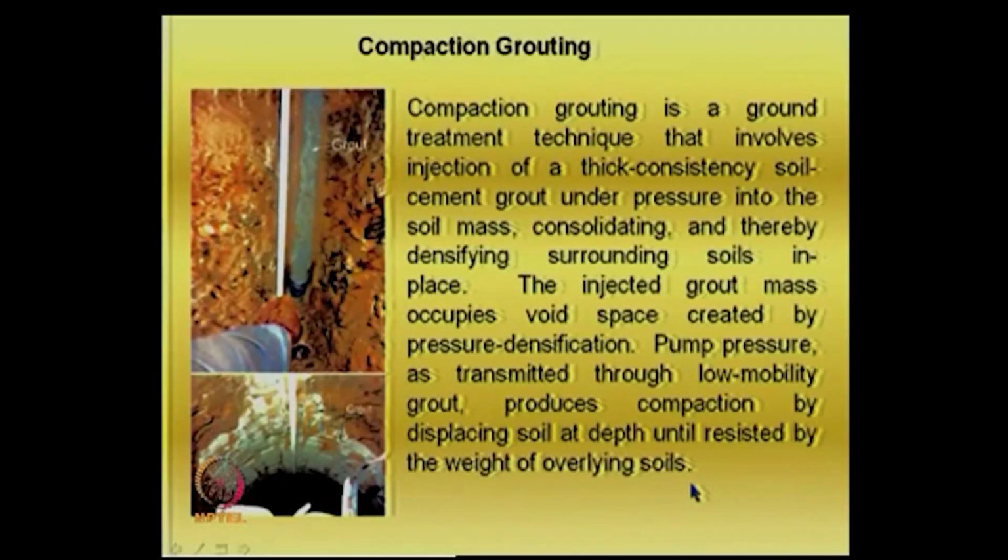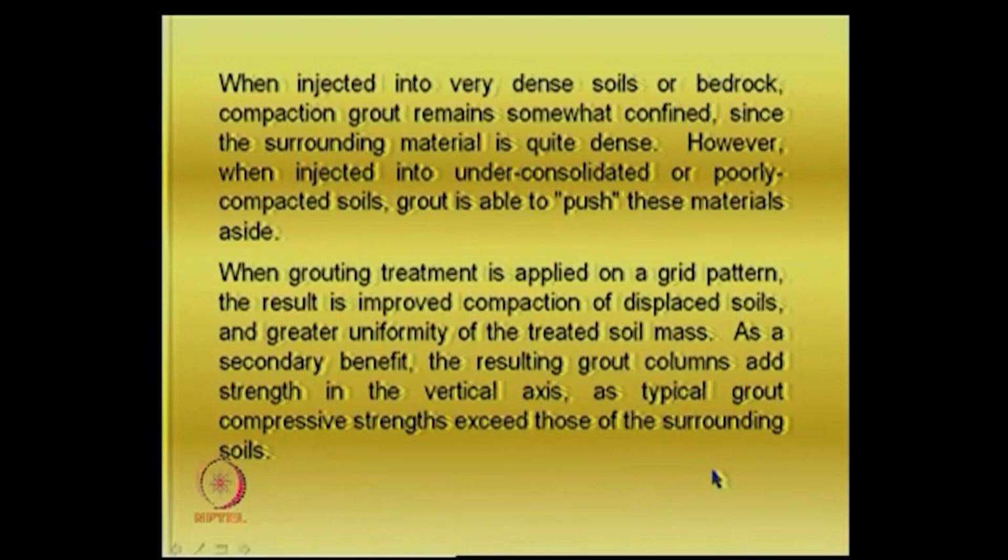That is why you just see the formation of bulbs and strong substances. When injected into the dense materials of bedrock, compaction grout remains somewhat confined since the surrounding material is quite dense. However, when injected into under consolidated or poorly compacted soils, grout is able to push these materials aside.